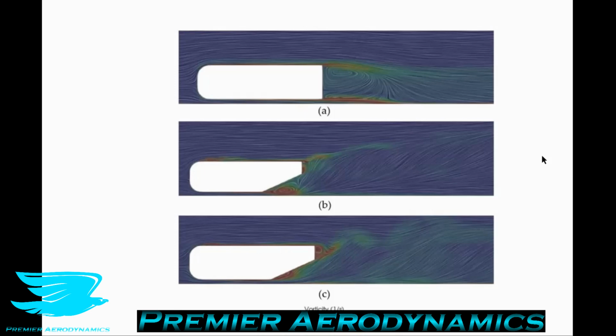Apart from that, we do get quite a few major vortices around the lip of the diffuser, so the inlet of the diffuser, for these two other configurations, the one with the diffuser and the one with the airfoils. But for the armored body without any diffuser, there's this massive asymmetry. Because it's close to the ground, no real vortex can roll up close to the ground. It's really squished. But at the top of the armored body, behind, there is this major roll up, which I have seen in our CFD simulations.